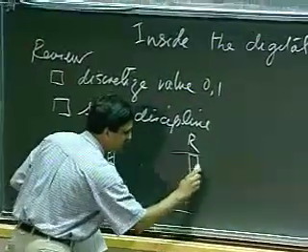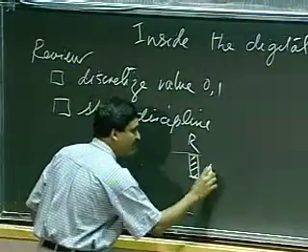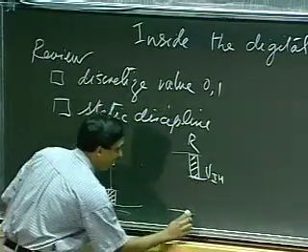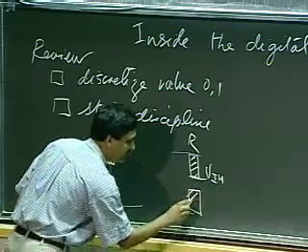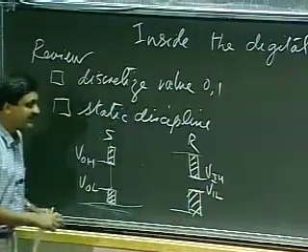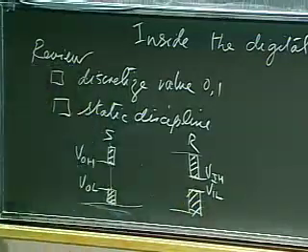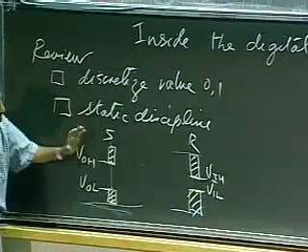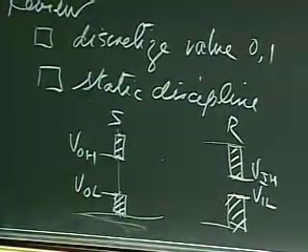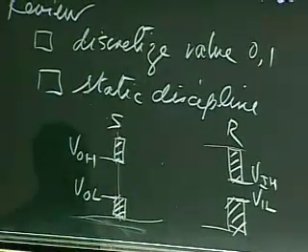Okay, similarly, if I was a receiver, then I had to guarantee to recognize as a 1 all voltages that were above some input high voltage threshold. And similarly, I had to guarantee to recognize as a 0 voltages that were below some input low voltage threshold. Okay? So provided senders and receivers in a system adhered to these voltage levels, to this discipline, then they would all very comfortably work correctly in a digital system.